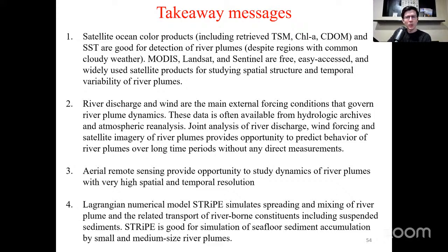Thank you. I think this is a pretty good answer. The second question is, which satellite data performs best, and what is your recommendation for mapping the river plumes? My recommendation, for example, is that you should find the spatial scale. If your plume is less than 1 kilometer wide, for sure you have to use only Sentinel and Landsat, because they provide several dozens of meters of spatial resolution, and MODIS, which is 250 meters, will not be useful.